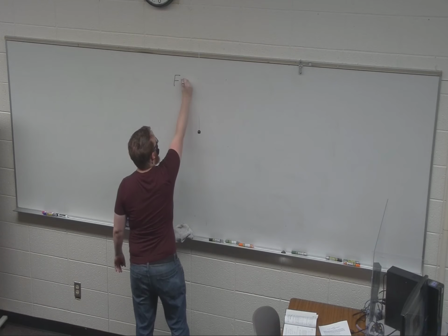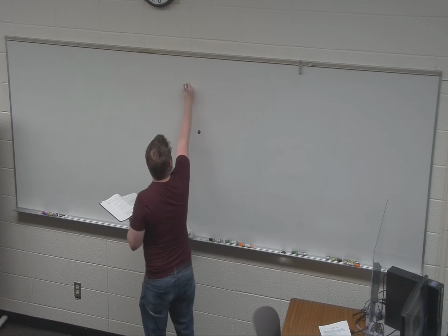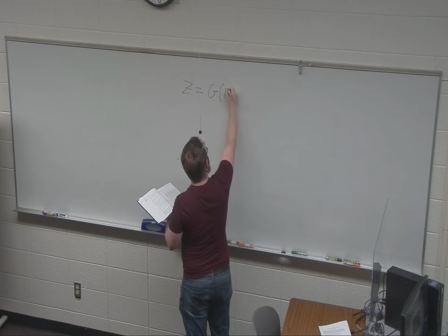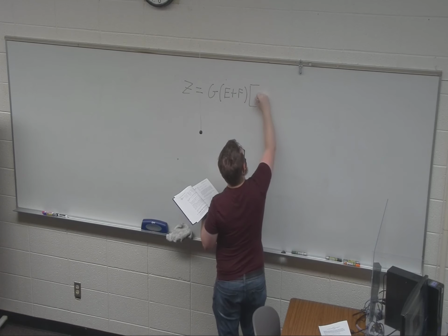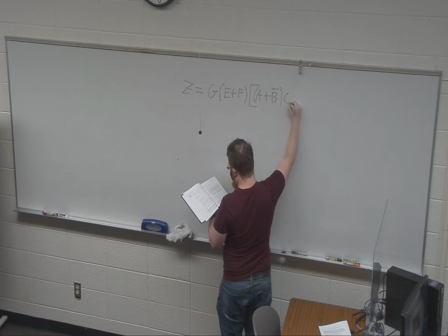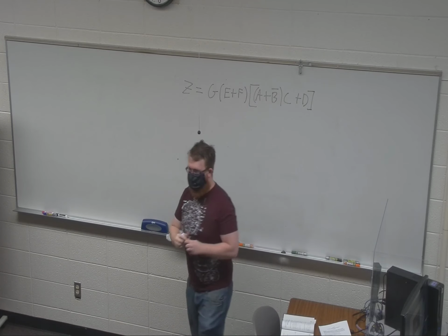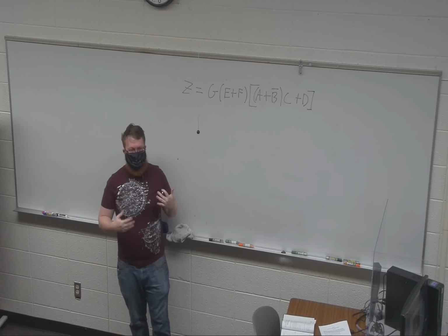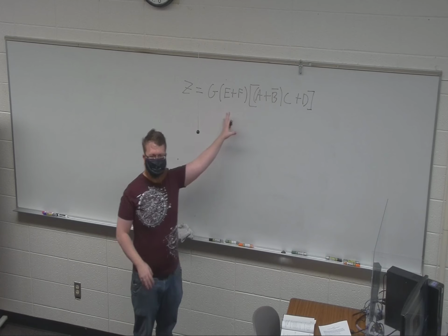So if we have this function, which we'll start right with, it must be Z. Okay, so if we start with this type of an example of a function, and we want to turn this into gates, it tends to be easiest for us to think of AND OR, especially because this is the kind of function that we'll get out of a K-map, right?